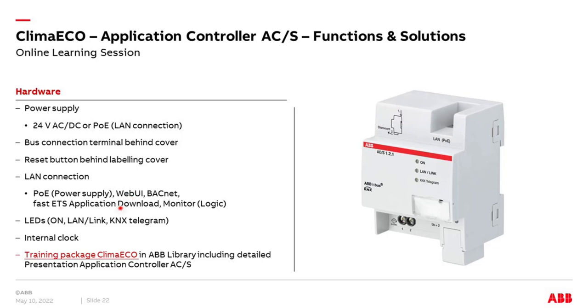For the fast ETS application download, it's really recommended to always have an IP connection available. You save really time compared with programming via the bus connection terminal. And if you have your own logic created, we have a so-called online monitor available there. You see directly, if you take action in your installation, what happens with your logic. And for this purpose, you need also the IP connection. I will show it to you also on Thursday in our practical demonstration. Yeah, we need an internal clock because we have a lot of time functions. We have this scheduler, we have this data logger, so all these time functions are connected.